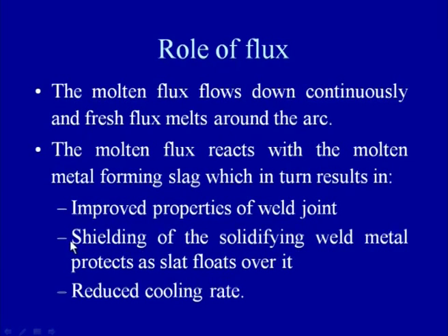So, here the slag being formed becomes lighter, and it starts to float over the surface of the solidifying weld metal, and thus provides protection to the weld metal. And further, the cover of the slag over the solidified weld metal reduces the cooling rate during the welding, and this reduced cooling rate in the case of hardenable steels helps in reducing the cracking tendency.